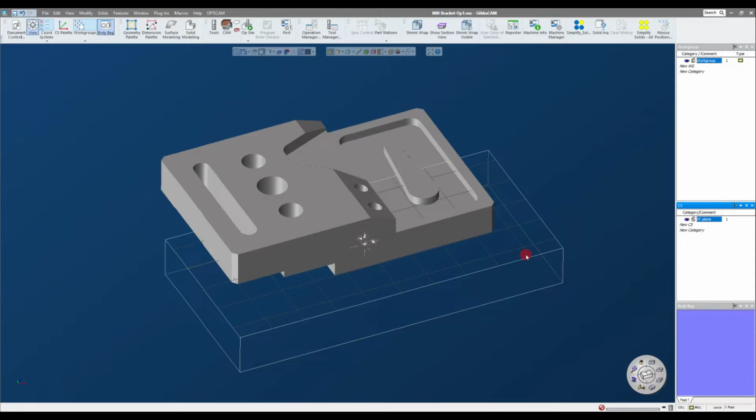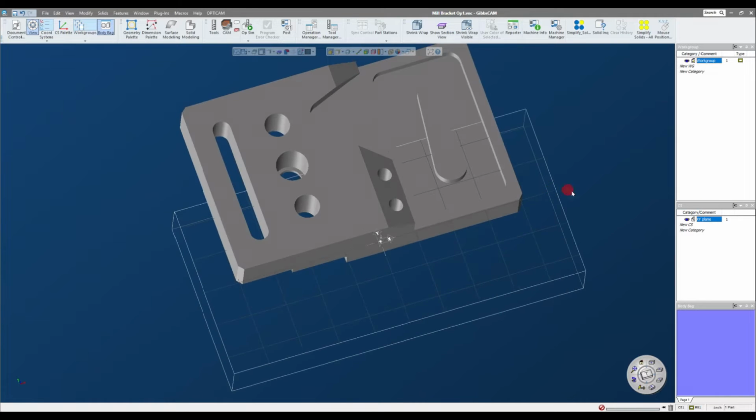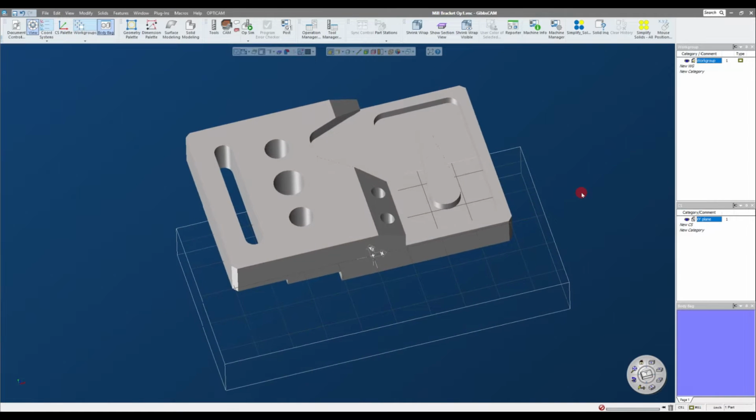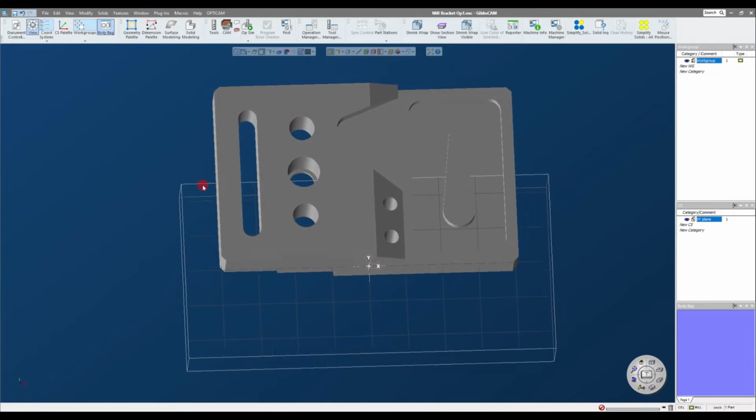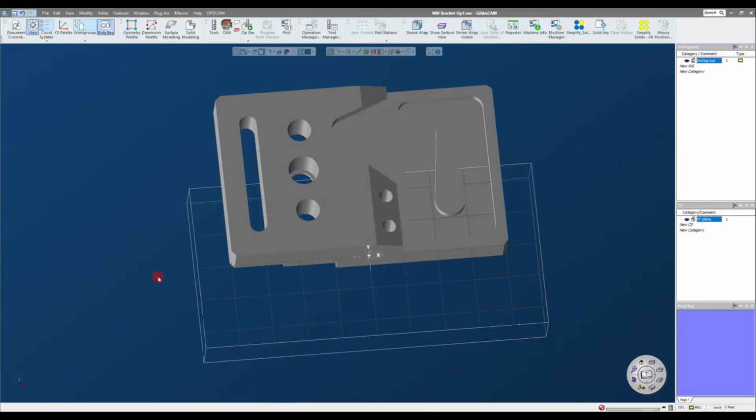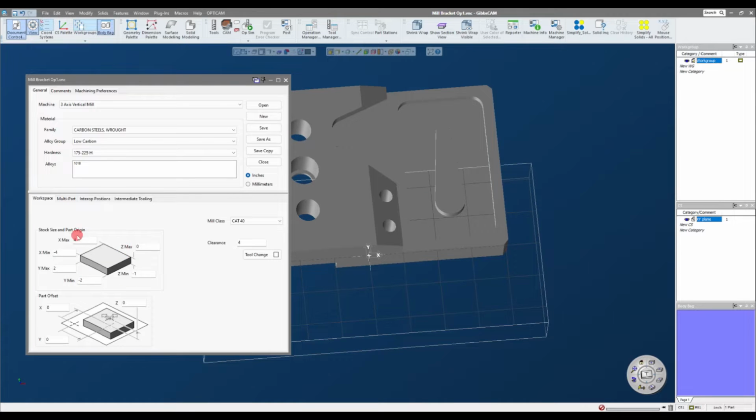When you're in CAM mode and you're applying toolpath and work offsets to your part, you do want to keep those because those are being used. Coordinate systems are used in two ways, to orient and also to machine. So for right now, all we have is my XY mode, master or clearance plane. So now you see that my stock is drawn, and the stock typically comes in the shape of the last part you programmed. And that's going to be listed in my document control here.